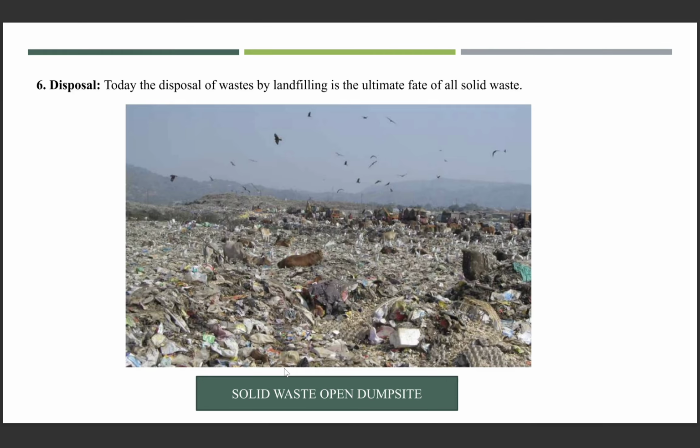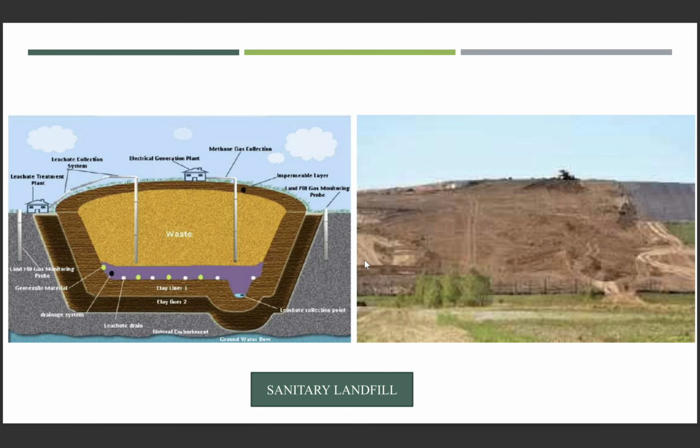The solution for these types of dump sites, where waste is dumped in the open and no cover is given to the waste, that's why it has attracted a lot of these creatures. So the solution is the sanitary landfill or engineered landfill, where first of all the land is lined using some geomembrane so that landfill gases and leachate do not percolate into the soil and subsequently into the groundwater.